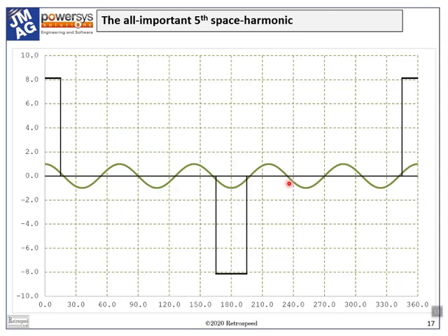And in this sense we have a classical synchronous machine. It's a little bit counterintuitive to think of all the harmonic poles of MMF interacting with all the 10 poles of the magnets. Surely the harmonic poles of the MMF are fictitious, except possibly at the physical locations of the coils.